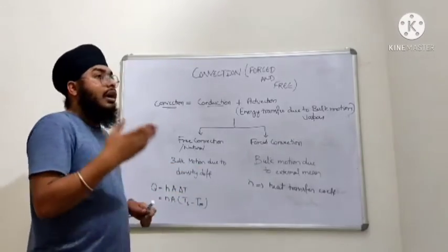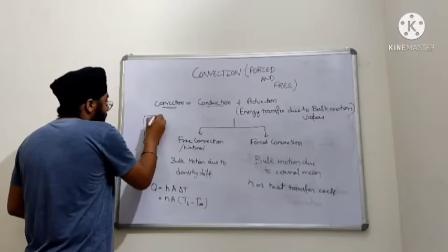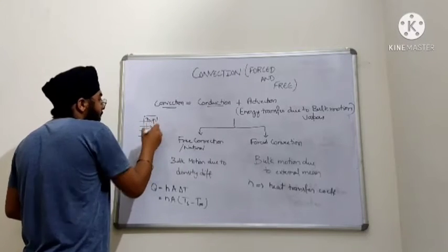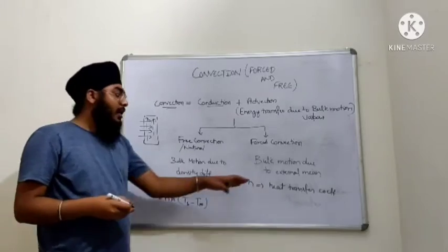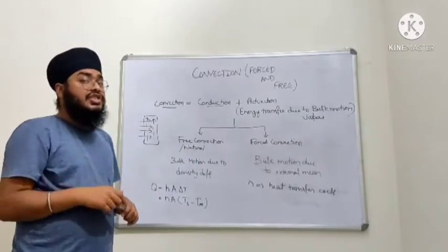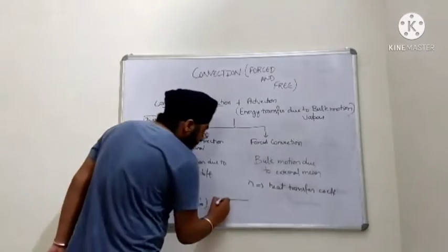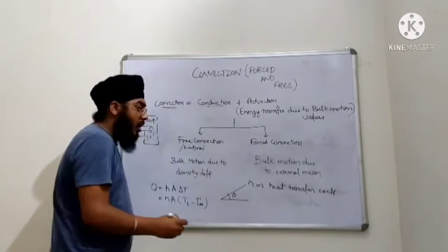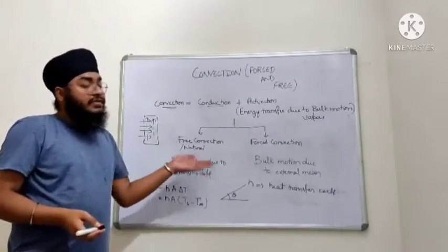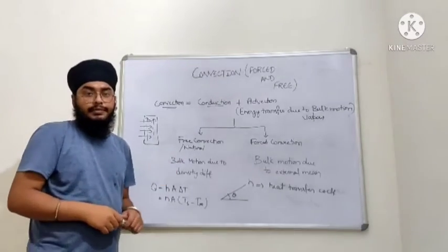Other than that, direction is also a factor. Like if the fluid is going breadth-wise or length-wise, in both directions, H will be different. After that, the orientation can also be a factor, like if the surface is horizontal or at an angle theta to the horizontal. At last, H will also be affected by the thermophysical properties of the liquid.